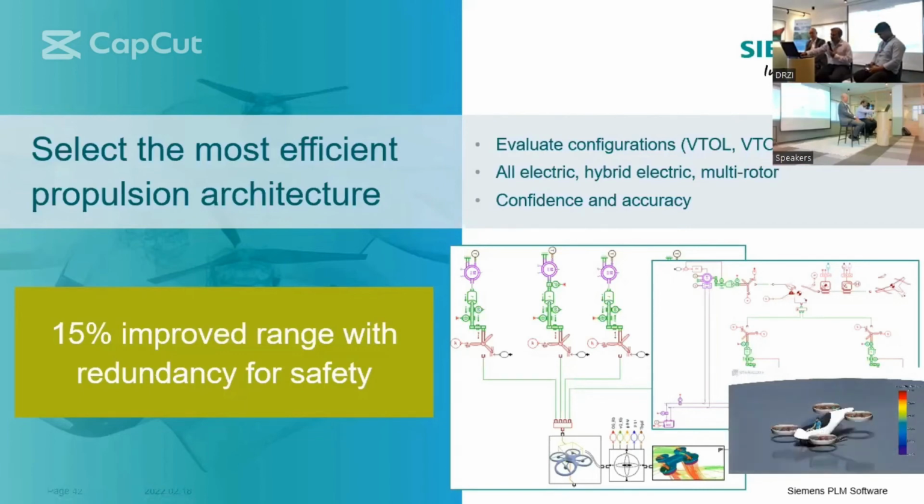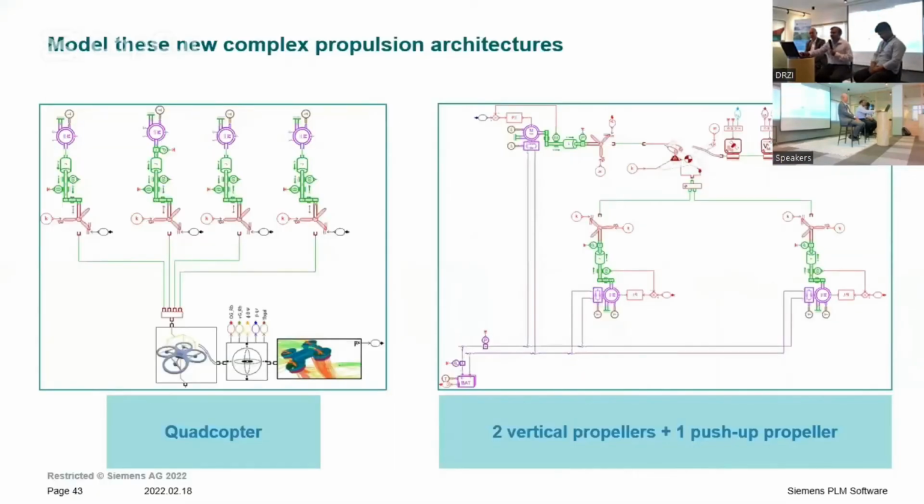So the simulation helps to see at an early stage whether this concept is good or that concept is good. Then how I can make my propeller very efficient. If I use a different gear ratio, can I make it fly more efficiently, right? If I change this bigger motor to a smaller motor, will I save my battery or not?